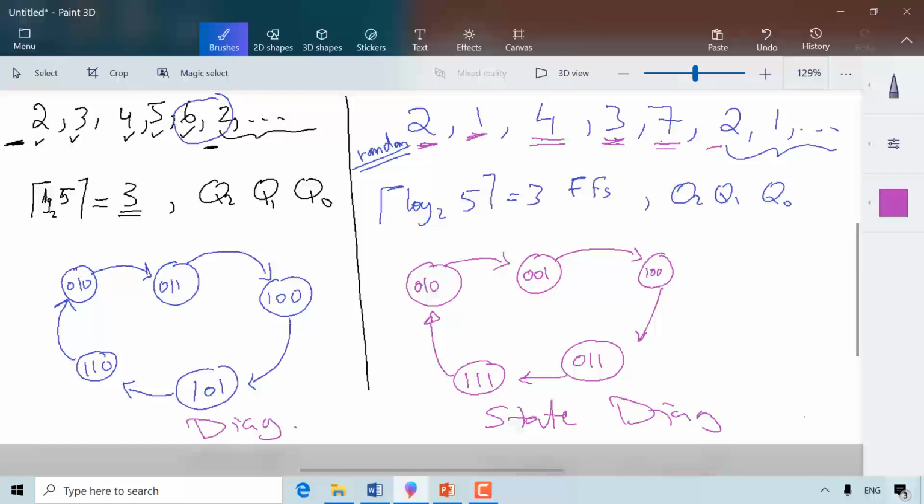We're not going to continue with the examples because I think we have gone through enough details that you can carry on with the rest of the process yourself. So we just illustrate the hardest point, which is getting the state diagram correctly. Because if in the assignment or the exam you start with a wrong state diagram, the whole problem solution is messed up. So be careful with the state diagram because it sets the tone for your answer.